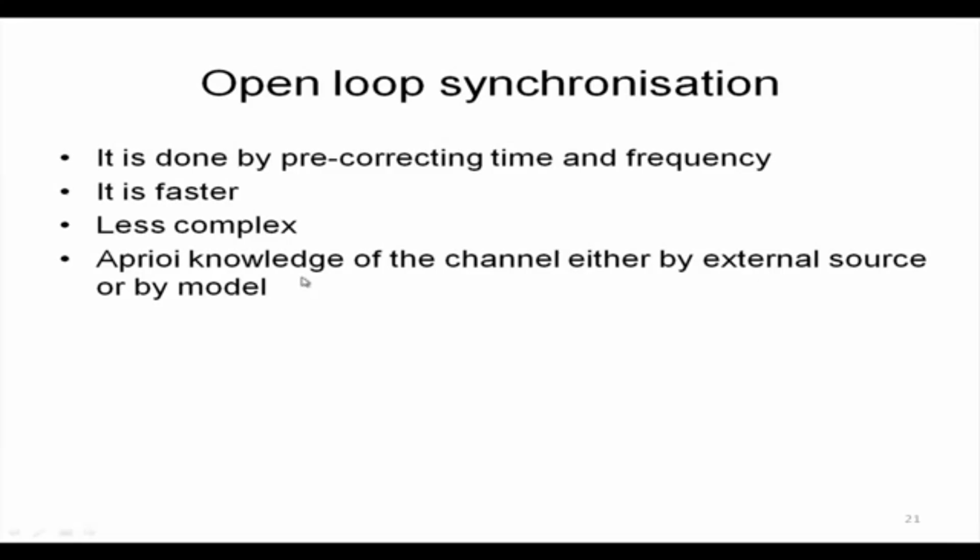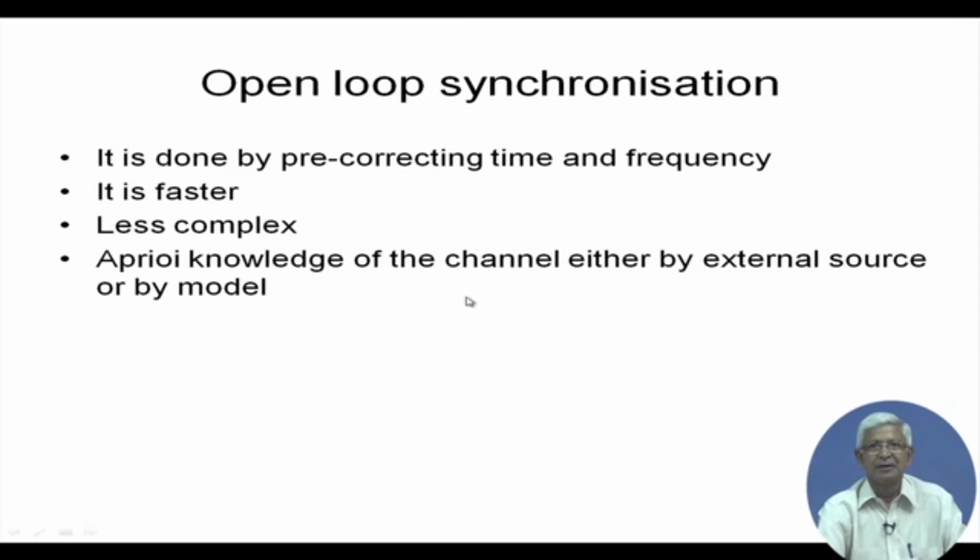If that model is supplied to the individual transmitters, the earth stations, they have their own location, and from the model at a particular time they can find out the position of the satellite as per the model, and as part of that they can find out what the propagation delay should be between the earth station and the satellite. So, it can be modeled or it can be known from the external source.